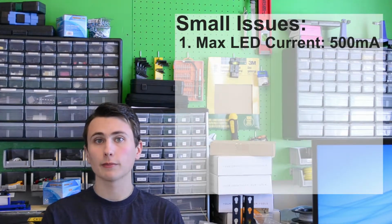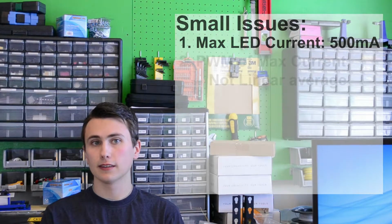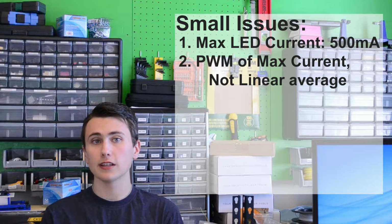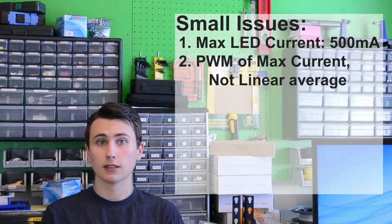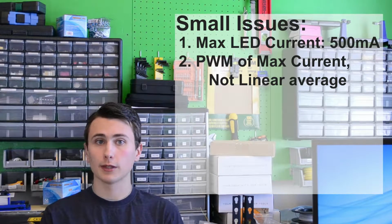Like we talked about in episode 9.5, this was most likely a chair-to-keyboard translation error, and this is what happens when we aren't diligently inspecting the critical sections of every part's datasheet. I'm sure that this behavior, the pulse width modulation of the maximum current, is explicitly called out in the datasheet for that current regulator, and I missed it.